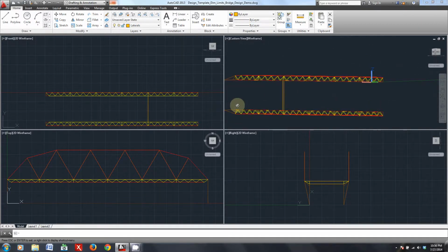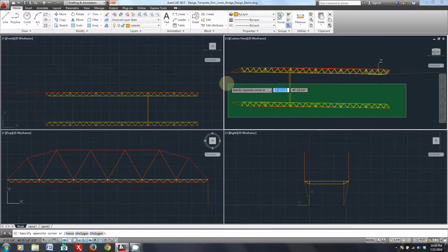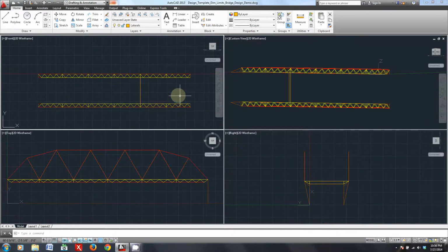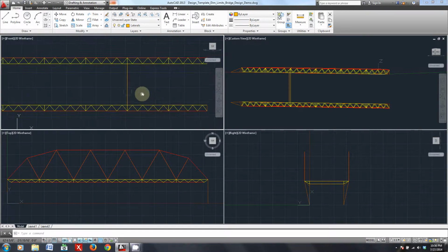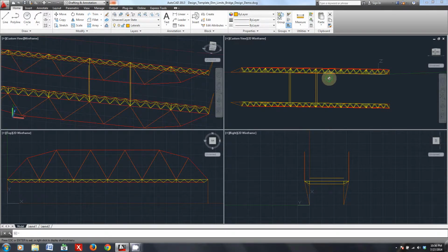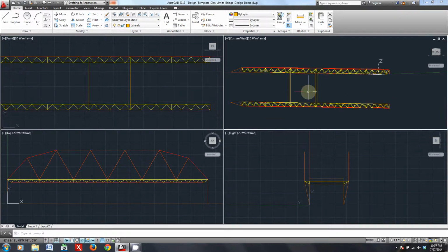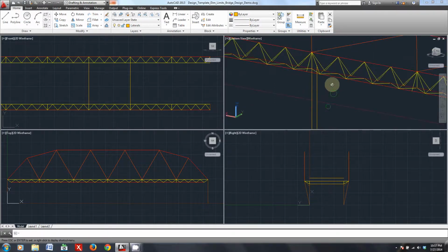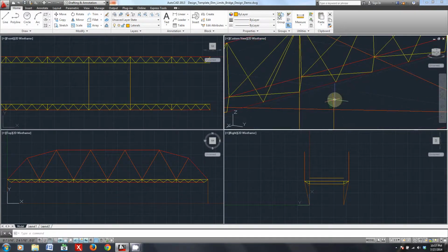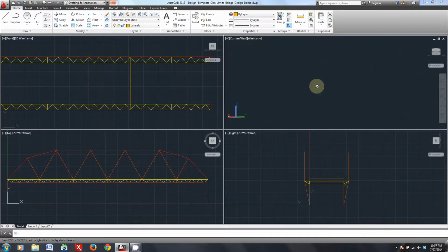However, there are a couple of issues that I would like to point out if you're dealing with something in a 3-dimensional sketch while looking through a 2-dimensional viewport. Let's say I wanted to copy this over to some other location, and I'll go in 2D and say I want to go here. Now there's a 50-50 chance that this might give a poor result, and in fact, let me take a look. Oh, oops. So this is the one we just copied, but check it out. Technically, I wanted this line to connect to this line, but for some reason, it didn't do that.